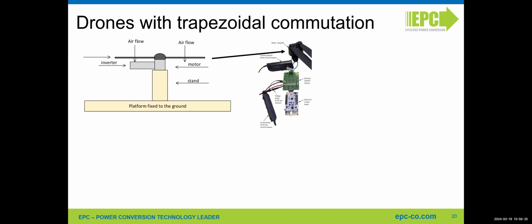If you're doing field-oriented control, sinusoidal, sensorless or with sensor, it doesn't have to be sensorless. With sensor, then even the locked rotor is something that you control, because you control the current all the time.